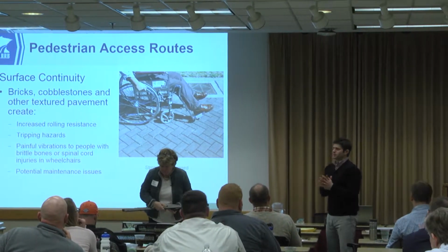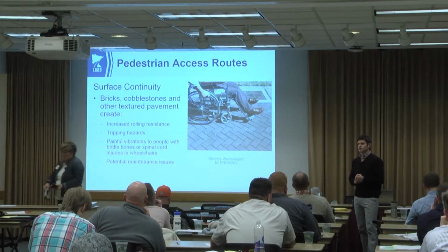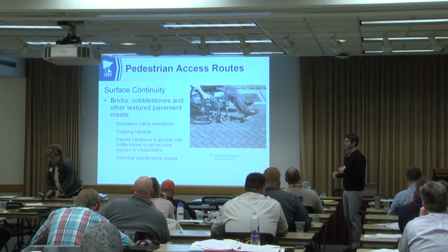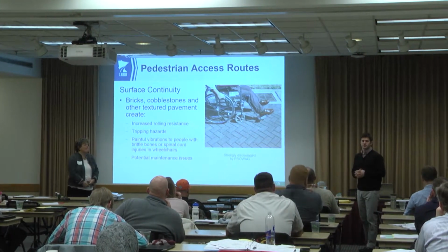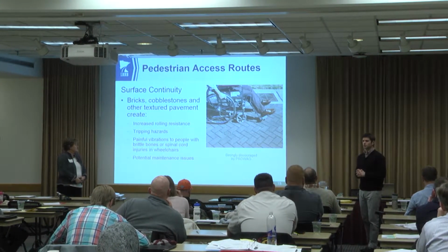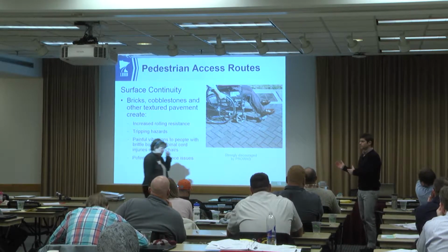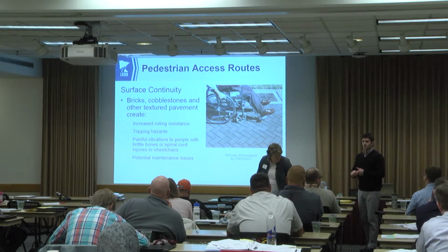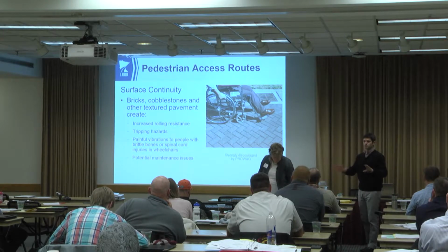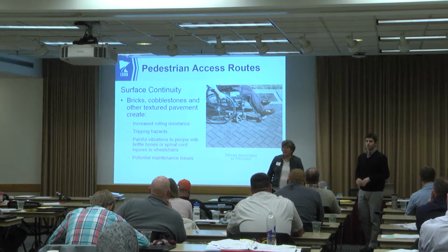At this point, they are still technically compliant, although there's a better choice to use. And in the future, there's a new sort of roughness standard that's going to come out. I don't know when, but it's going to be used to help determine whether it's compliant or not. On projects that we've worked with MnDOT on, MnDOT has been saying no pavers in the right-of-way, or in the access route, period. And so we may go that way where you can't do it.